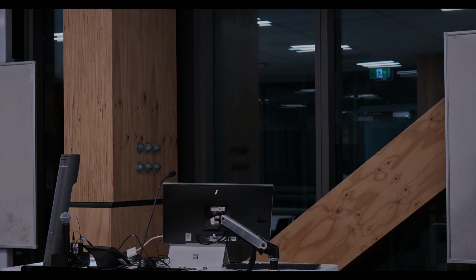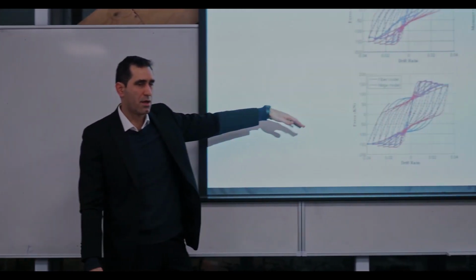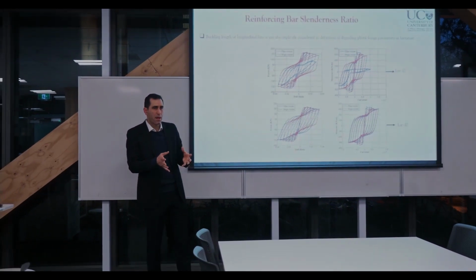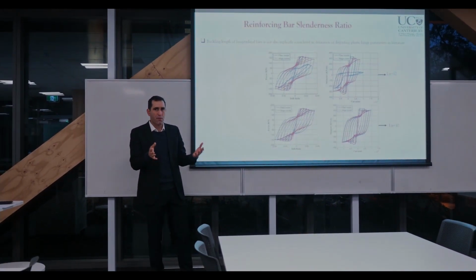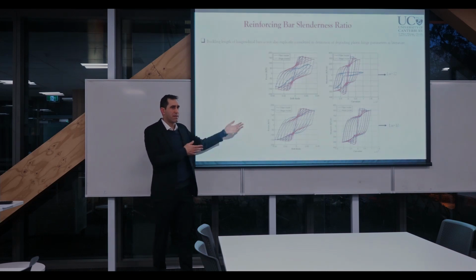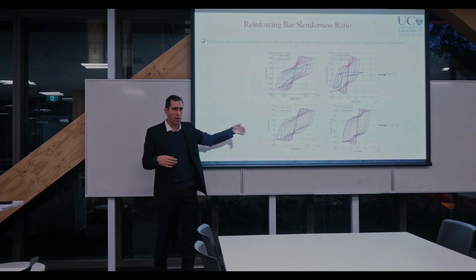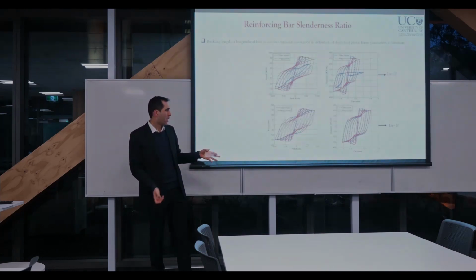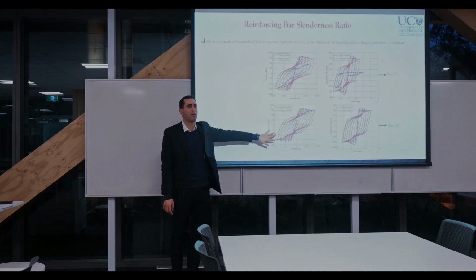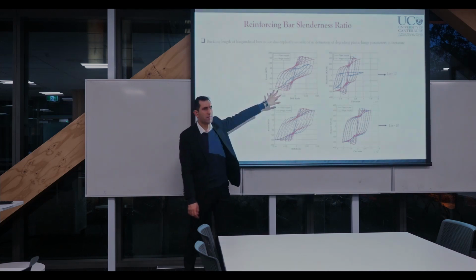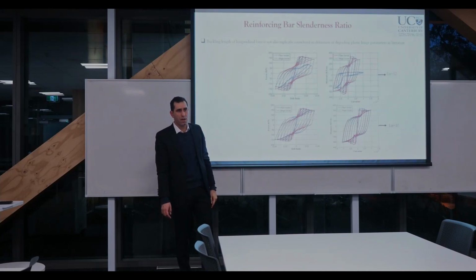What I have observed, as you can probably see in the curves below, is that generally speaking, LSR is neglected in those studies. So if we take a low LSR and detail a section with closely spaced stirrups, with the lumped plasticity models we get very good behavior. The parameters become such that we get a lot of interstory drift or plastic deflection limit. That pretty well matches with the fiber model if we use low LSR. But as soon as the LSR goes even slightly higher, the difference starts to show. This is what I observed.